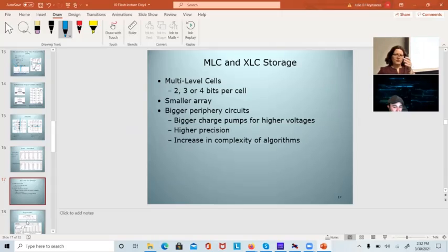And I probably am going to program them on the low side, because as the read disturbs and programming disturbs go on with time, I'm going to increase all those threshold voltages a little bit.